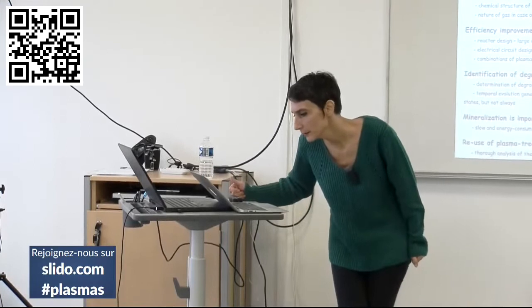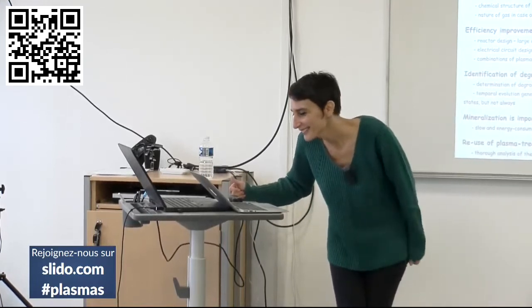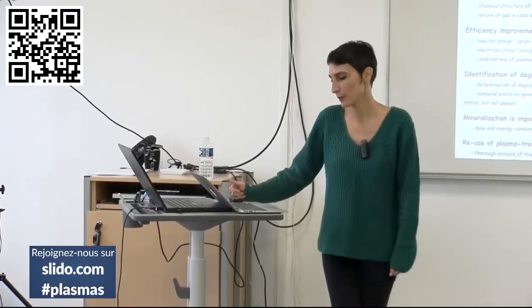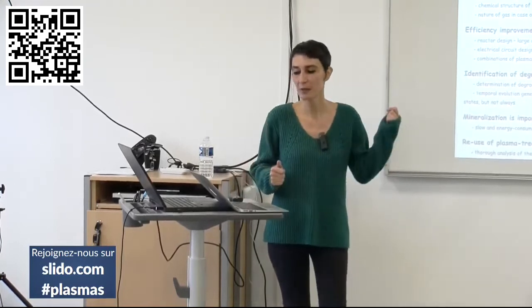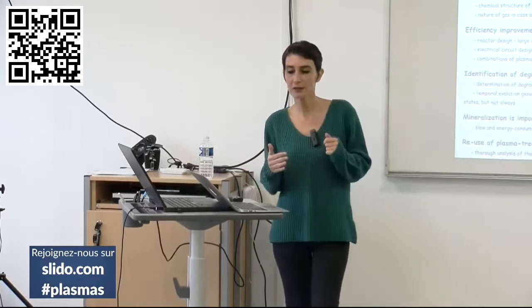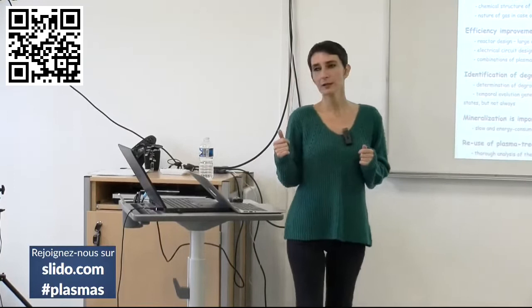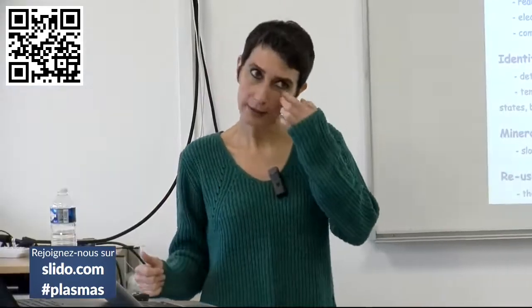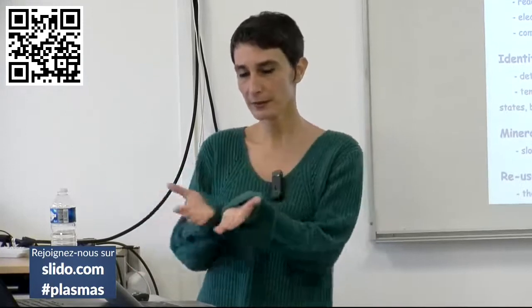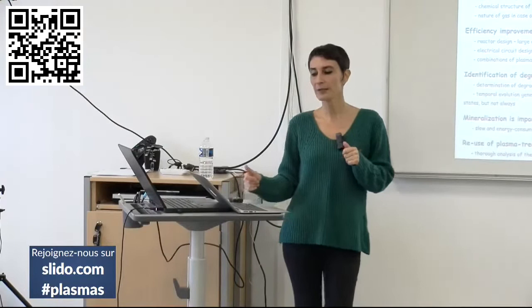And the last one, or I don't know if it's the last one, but the last one here, how is the concentration of OH measured in the process? Yes, I should have mentioned this during my presentation. So OH measurement is not a trivial thing. We are using a chemical probe, 3-carboxycoumarin acid, to measure the concentration. This compound, 3-CCA, reacts with the OH and forms another product. So OH is attached somewhere in the 3-CCA molecule and forms a fluorescent product. And this product can be determined by HPLC, by liquid chromatography.